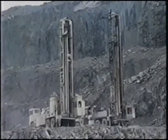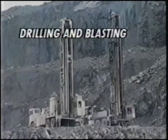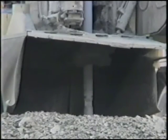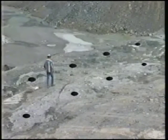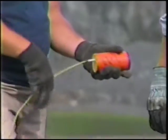For hard rock deposits, drilling and blasting is a necessity. The purpose of drilling and blasting is to achieve the initial fragmentation of the stone deposit. The blast holes are drilled in a pre-calculated pattern depending upon the type of deposit, drill hole diameter, and the hole depth. The spacing between the holes is scientifically calculated in order to ensure maximum fragmentation of the rock while minimizing ground vibration and noise.